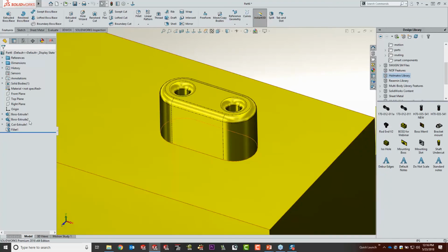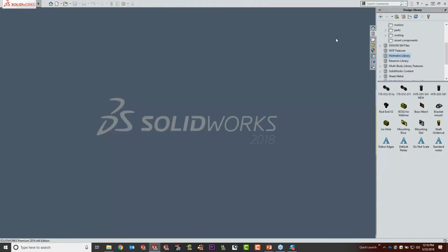And if you notice it over in the feature tree, the three features that I actually selected prior to dragging them into the tree, into the folder, now have an L on them, which indicates that they're part of the library. So it's a really cool behavior. Now to use this, it's simply the process of using some of the drag and drop methodologies.